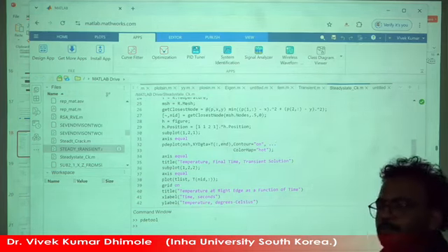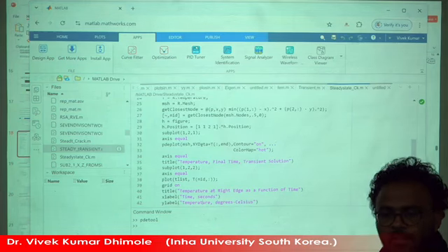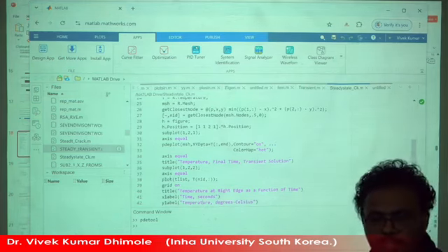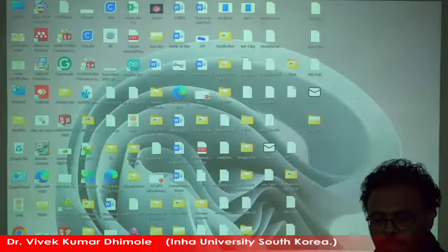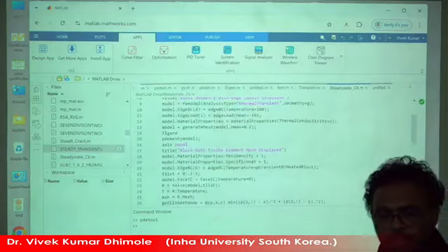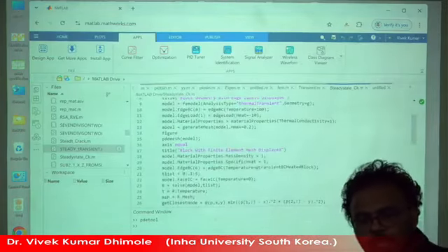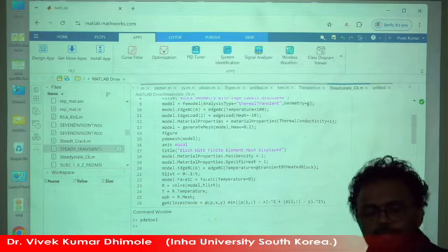In Python you can use the plotting tools, the PyTool, something like that, and the shape figure, something like that is there in Python tools also. And here is the PDE plot. A direct plot command is there. The cubic plot command is there, so you can use those plotting things here. So this is the way to do it in MATLAB by command, and I will show you the GUI as well from here. Here you can type pdetool, and it will open the GUI as well, right.